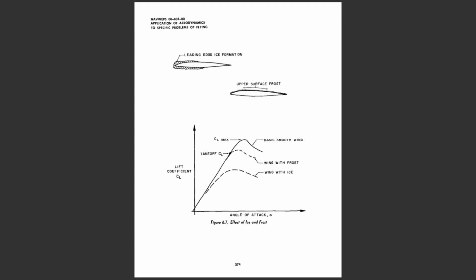The effect of ice or frost on takeoff and landing performance is of great importance. The effects are so detrimental to the landing and takeoff that no effort should be spared to keep the airplane as free as possible from any accumulation of ice or frost. If any ice remains on the airplane as the landing phase approaches, it must be appreciated that the ice formation will have reduced CL-max and incurred an increase in stall speed. Thus, the landing speed will be greater.